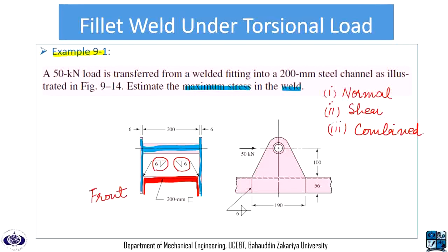We have the side view of the same figure available to us as well, and in the side view we can see that the designer wants us to have a fillet weld of leg 6 on the left side as well as on the other side, which is our right side. And from the front view we know that a weld is required at the top as well.